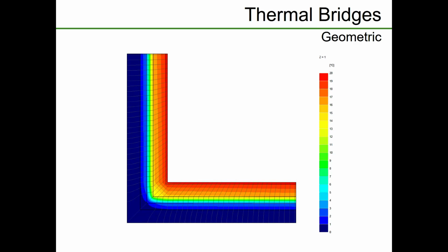When we look at the temperature distribution, you can see here at the edges of the model, the heat flow lines are perpendicular to the surface, which means it's going straight through. And this is a metre cut-off from the corner in this model. As soon as you start going towards the junction, you can see that they're starting to bend and be affected by the junction. So even that far from the junction, it's been influenced. Heat flow has been influenced by the junction itself. And you can see that in the temperature profile as well.